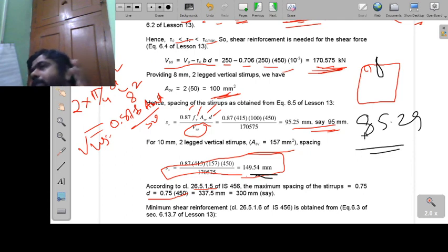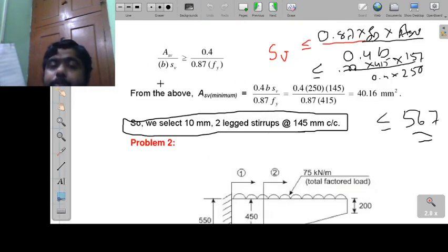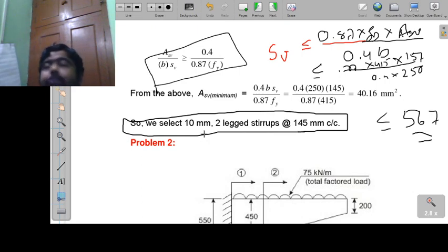Basically, whenever we go for a design of any kind, say single reinforced sections or double reinforced sections, whatever it is, everywhere we need to provide the shear reinforcement. Since initially we do not know what the shear reinforcement is, we do not provide it, but actually everywhere we have to provide shear reinforcement. So, we have to check by this: wherever tau v is coming less than tau c, it is not that we should not provide it, still we should provide the shear reinforcement. How should we provide it? We should provide it based on these guidelines. That means we should provide the minimum shear reinforcement in that case also.